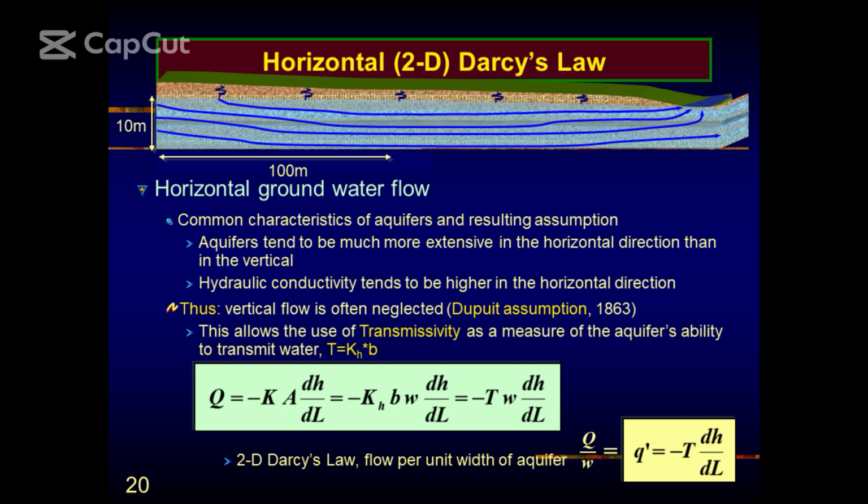That is very important. And if you check most of the texts, probably you will not find this explanation. But here, it has a significant role to play in groundwater modeling. Are you following? They'll just say, okay, transmissivity is equal to KB, and that's it.